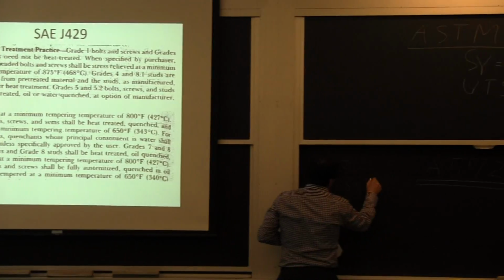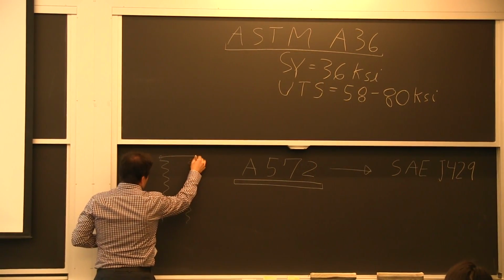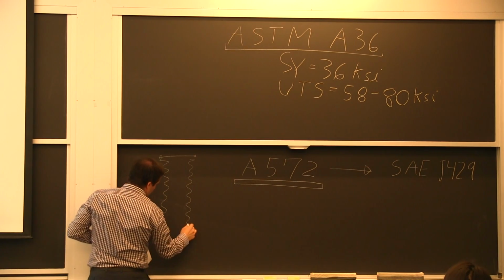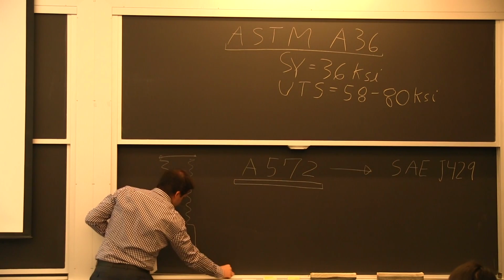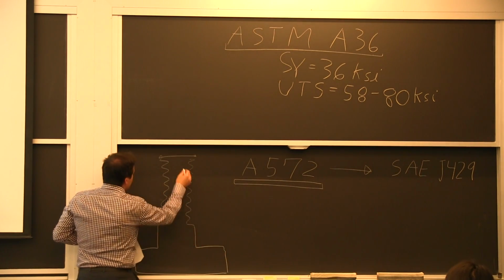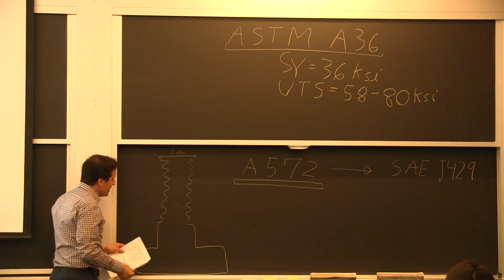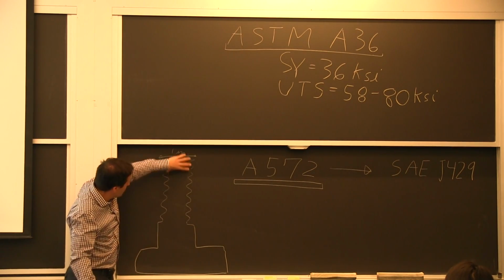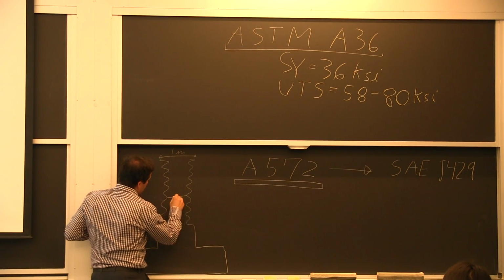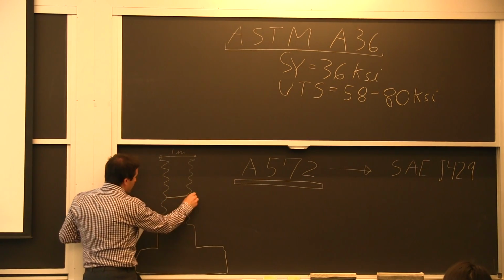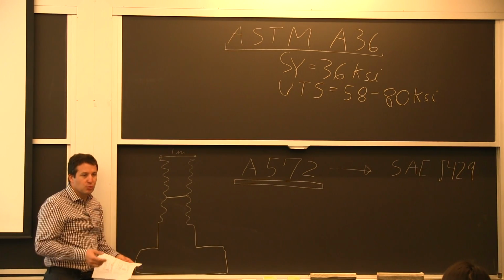A lot of times the way we do the analysis, you have the shank here where it's not threaded, and then you have the bolt head. If I start with a nominal 1 inch, it gives me a certain nominal stress through here, and then I have what we call a net stress here when I consider just going all around on the root of the threads.